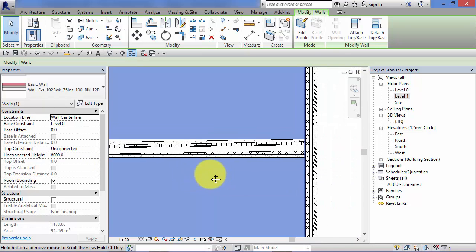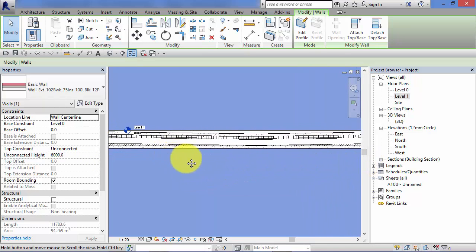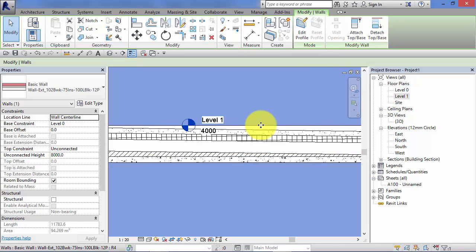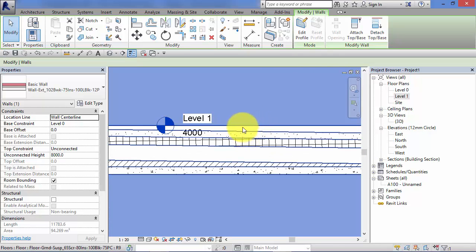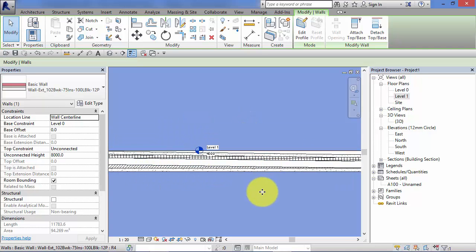So in reality, I would suggest for our walk-in shower room, we would set a screed layer at the top. We'd probably have maybe a vinyl layer for the floor finish. Then we'd have a screed layer up here which would be variable. That would form the tapered layer, and then the rest of them would obviously be horizontal beneath there.